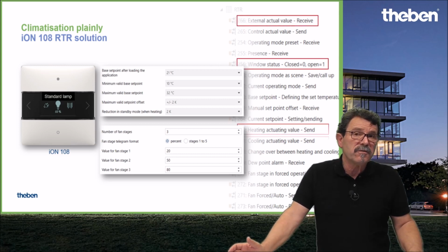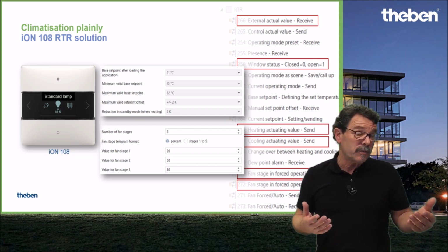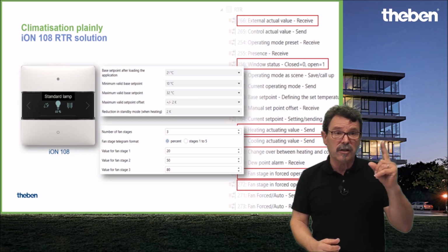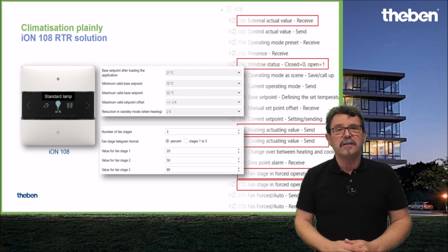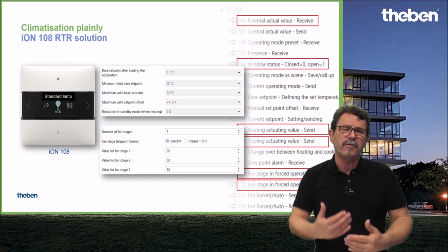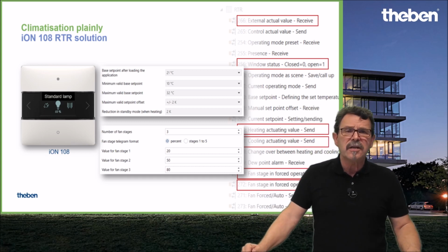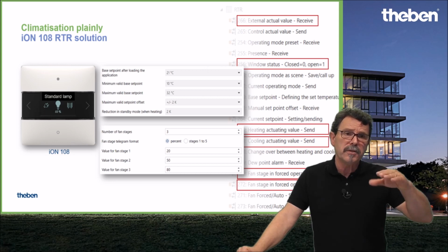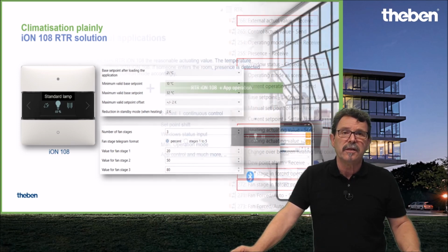What is the advantage? The advantage is that with 0 to 10 volt, you can adjust your desired speed control steplessly, especially when we have air exchange systems, tubes, for instance, in such kind of buildings here in the background. So probably at a certain speed, you will have some noise from the airflow. And during a conference, a meeting, or probably an official announcement from the board to the staff, it's probably not that comfortable to have this noise. With stepless control, you can really reduce the fan speed so that we have a really good airflow, but not this disturbance of noise. Due to that, it could be a big advantage to have this stepless control, or for instance, these systems have dampers, so then you can control the dampers. And most of the dampers, meanwhile, have to be controlled with 0 to 10 volt control commands. And the FCA2 can do this perfectly.